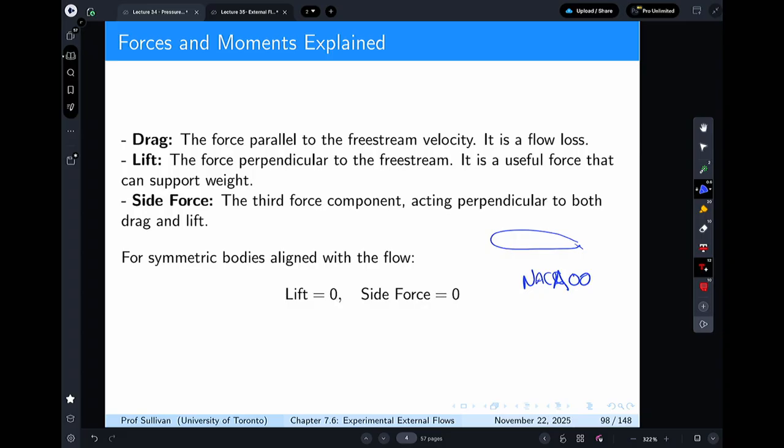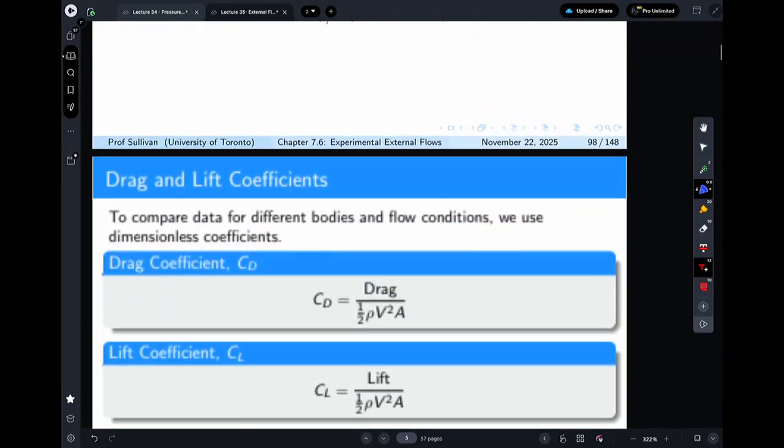And in fact, one of the greatest things that was done, from the 1920s, the National Advisory Committee for Aeronautics, did a whole bunch of wind tunnel tests. We use those wind tunnel tests and those tables to this day, despite the age, because we know a lot about them. Where we have problems right now is they did a lot of stuff at very high Reynolds number, above 1 million. Now we have a lot of small things flying, and we need to look at lower Reynolds numbers.